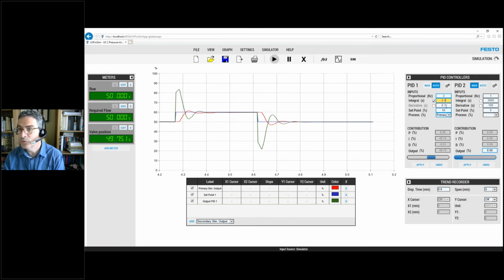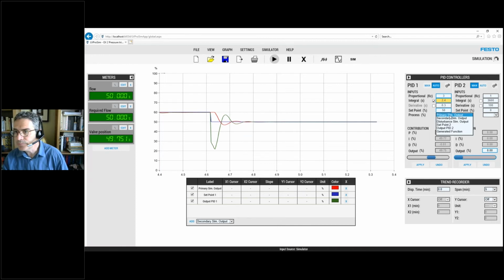And same thing with the derivative parameter. We would start with a low value, 0.1, double it to 0.2, then to 0.4. At 0.4, it will become too strong an impact. So in fact, let me show you here. Sorry, I will insert my derivative parameter and apply that.